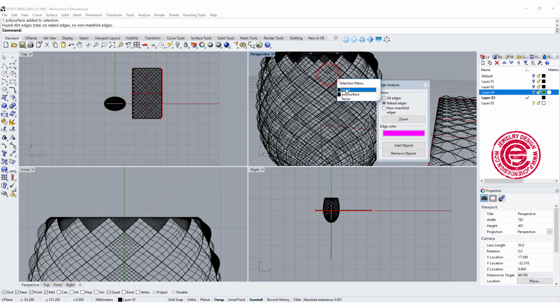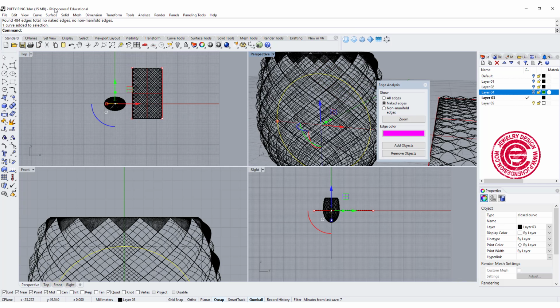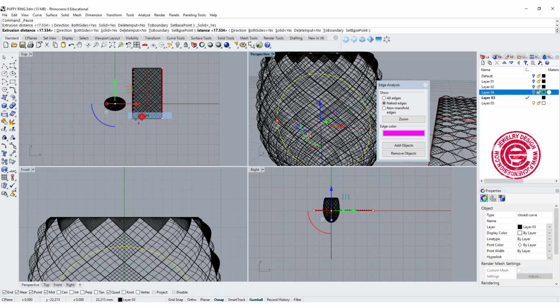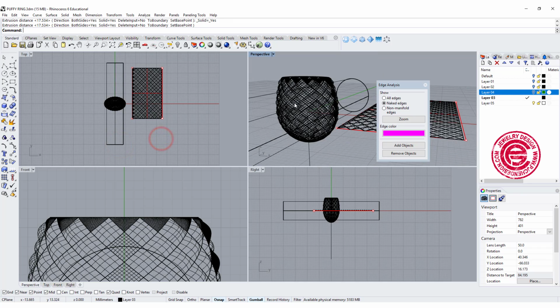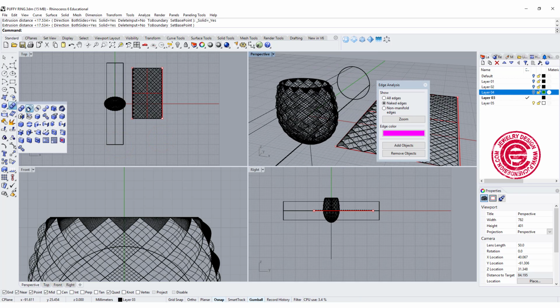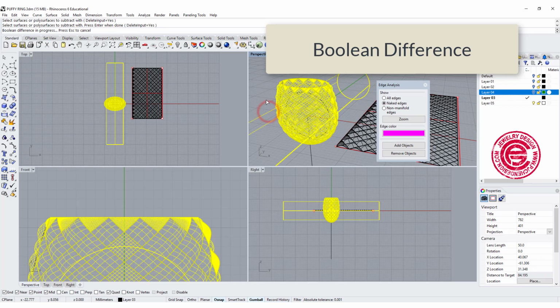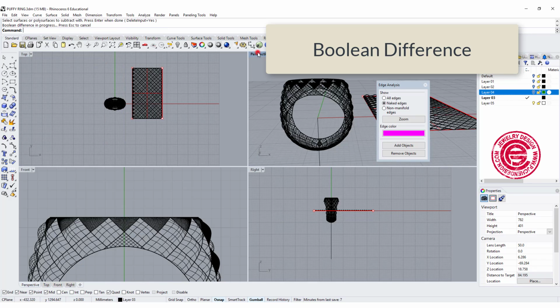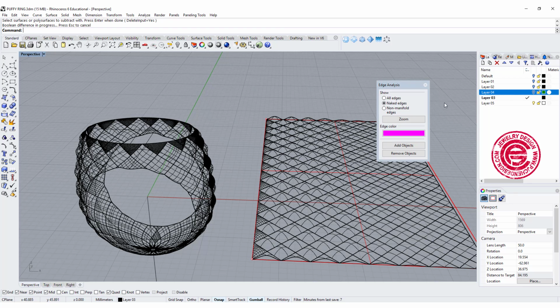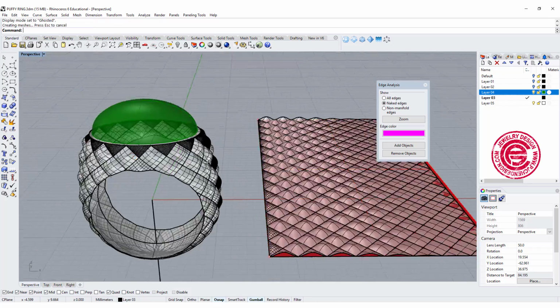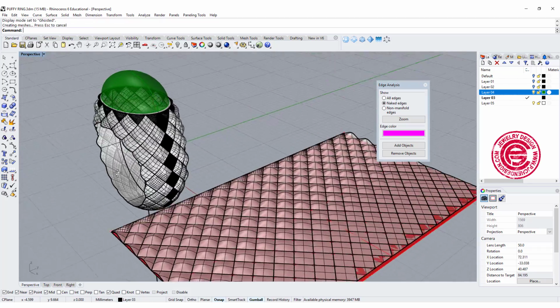We're going to pick up this curve right here for our ring size, and we are going to do the solid extrude planar curve straight like this, and we will need to do the Boolean difference. Pick up the one you want to keep, and this is our cutting tool. So then we will have something like this. We can turn on our stone that is on the top. Let's take a look on the ghost view. Alright, so that will be our ring today.